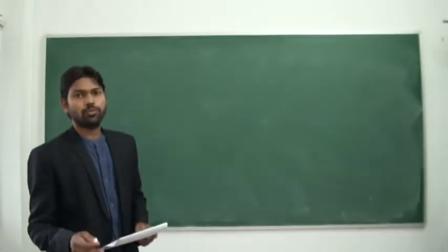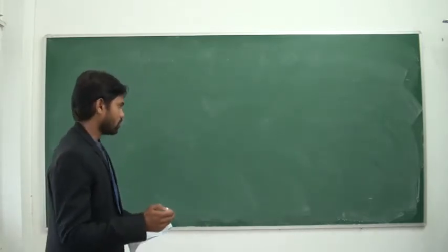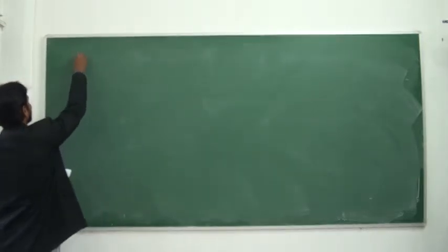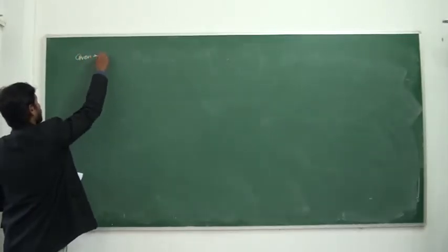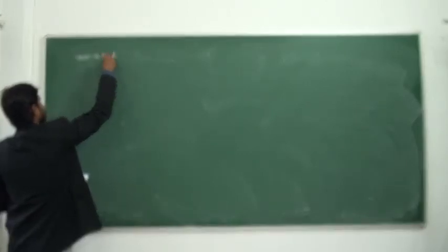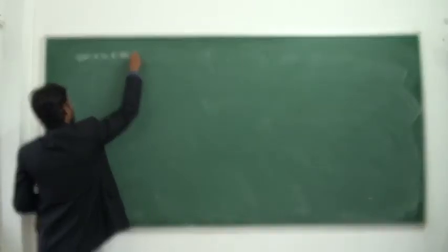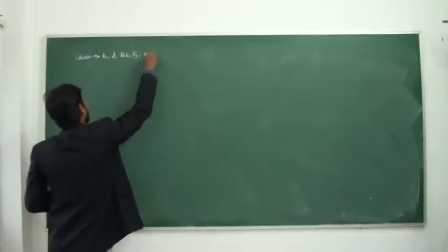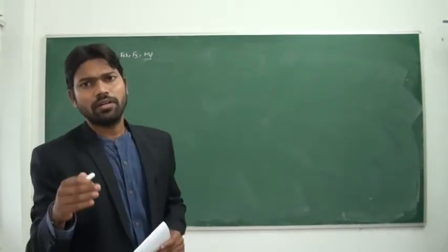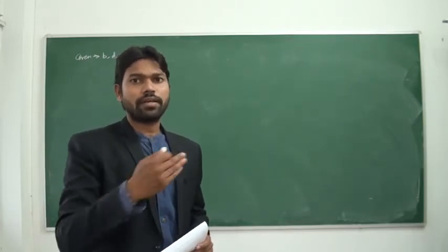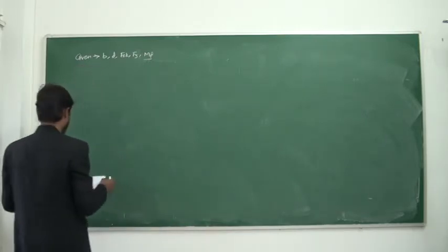So, what will be given in the numerical when they ask you to design? The given values will be: width of beam, depth of beam, fck, fy, and factored bending moment Mu (MD). But they will give you the working bending moment. You have to multiply it by 1.5 to calculate the MD value. So factored bending moment MD will be given.